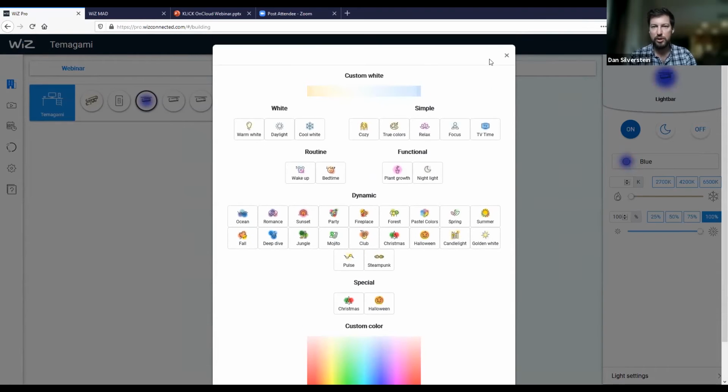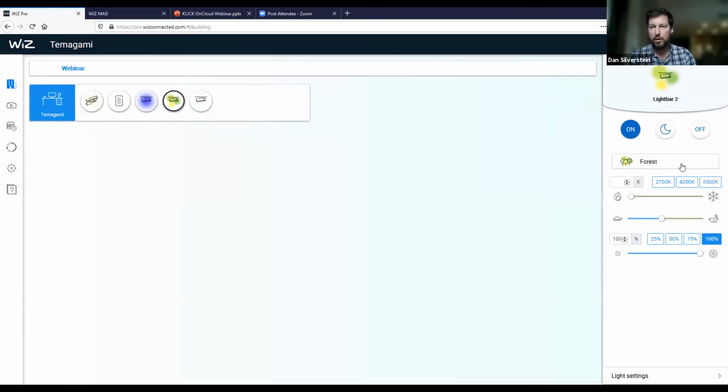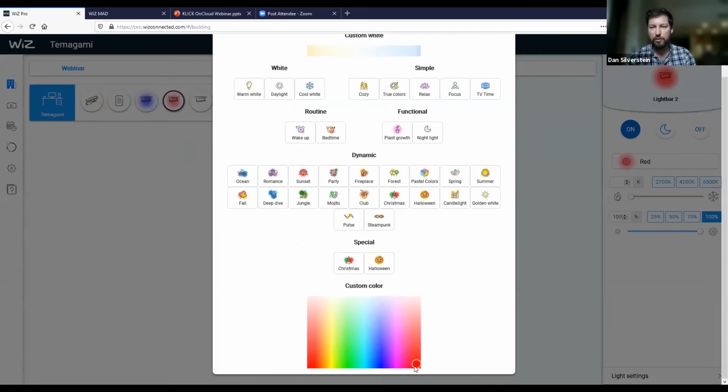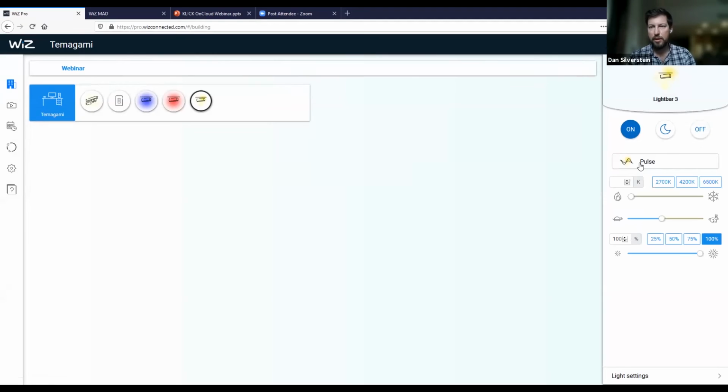Blues are kind of working. So we've addressed the first one. We can go to the second one and turn that on. I don't know, just to show that we've got the ability to try to find colors that render through the camera well. Nah, that's increasing the glare. Then right off the bat, we've got our 2700K, 4200K, 6500K, or you can hard spec the exact color temperature, we can go to 3300K, and hit that individually, dim them individually, control them.